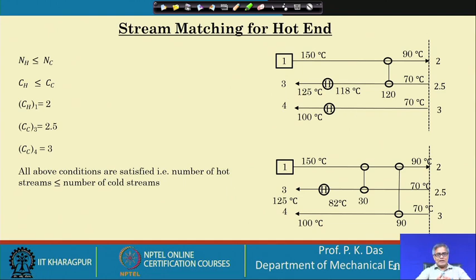Even more than that one can get in specific cases, and this is the flexibility of the design I am getting. With more number of solutions, I have neglected many of the practical things in a plant, like 2 streams cannot be brought together, or a heat exchanger with a very small capacity should not be used.